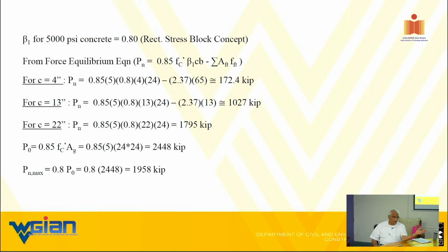Any way you cut it, the shear lag would be low and the bond strength will be high with smaller diameter bars. That's the way to go. But will you be able to satisfy the spacing requirements? It's always one thing or the other. It's a balancing act.